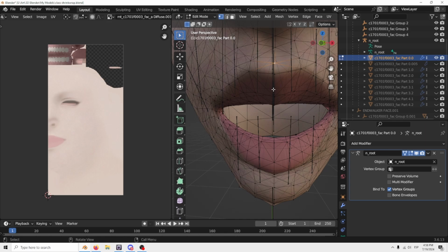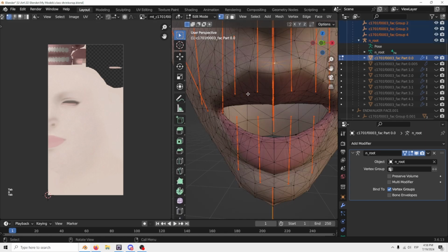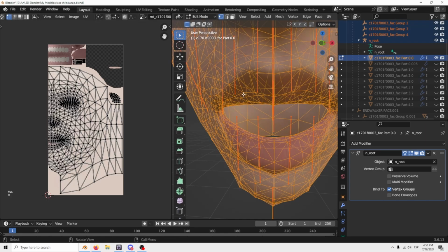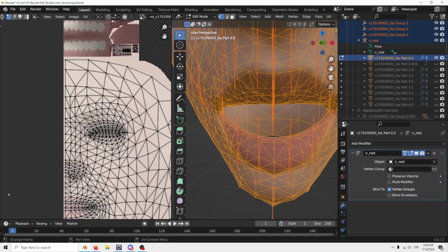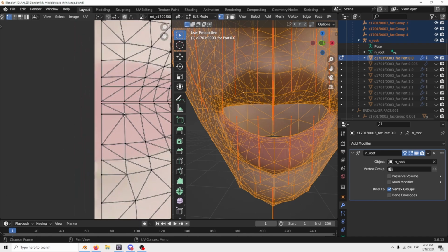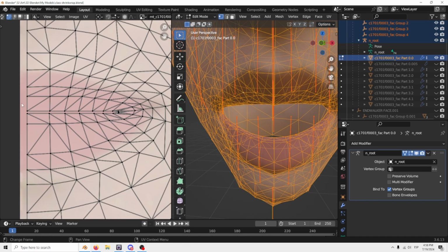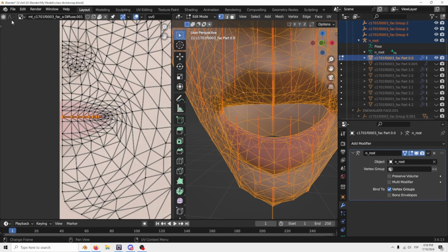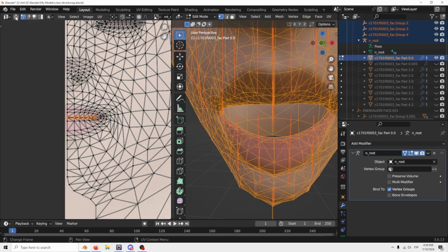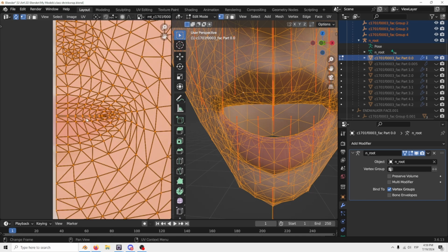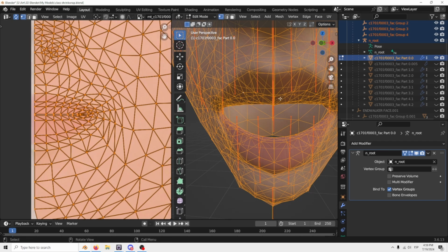And on this side, I'm going to select everything in edit mode and press A so I can look at the UV. If you zoom in, you will find that these over here are the area that we're trying to connect. In order to see it reflected in the model, you can turn on this little button that says UV sync selection. Right now it selects everything because everything is selected over here.